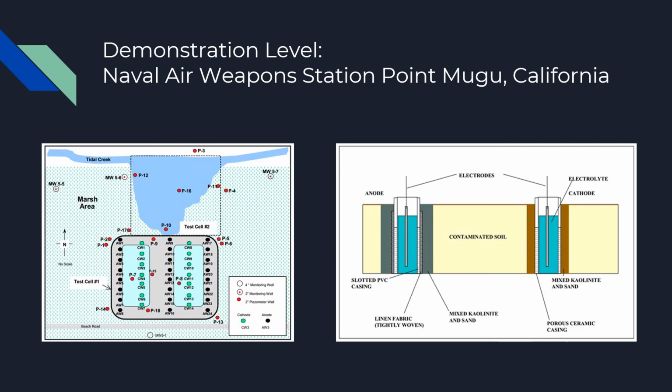The performance goal was to bring down the contaminant to California state regulatory levels, but no contaminant was extracted during this process, and samples were not collected after treatment. Hence, the target levels were not met. The transport of electrokinetically mobilized contaminants within confined and unconfined areas was not assessed since the performance was poor during the demonstration. The technology had an adverse effect on the organic contaminants of the soil since they showed an increase.